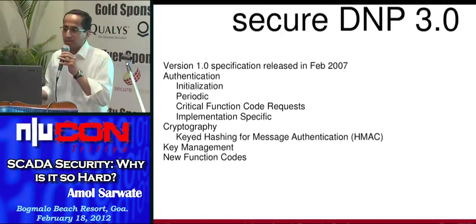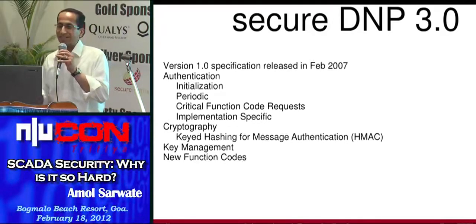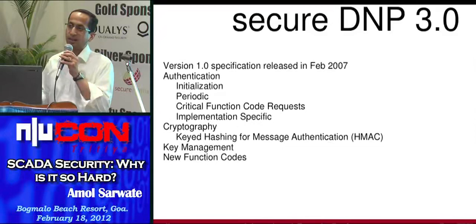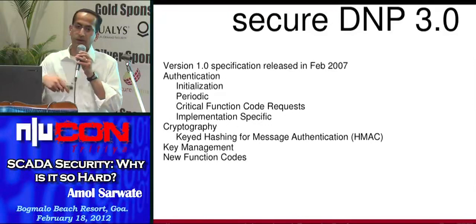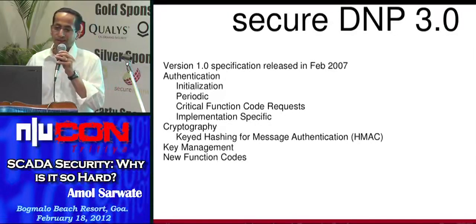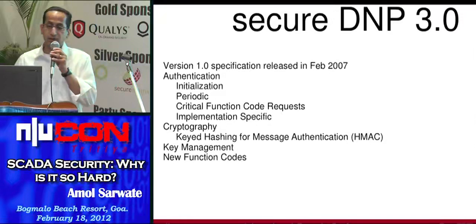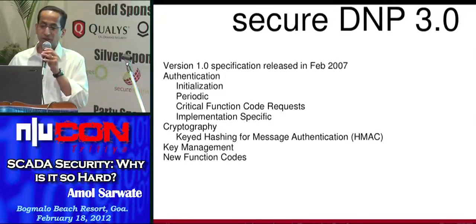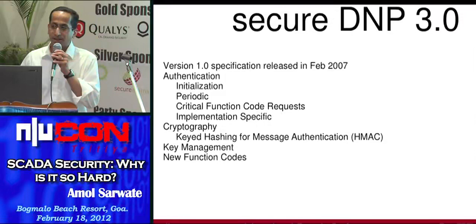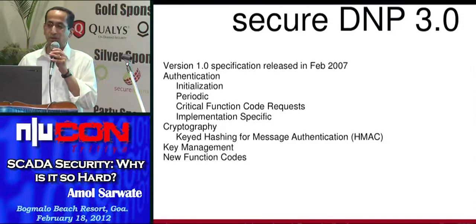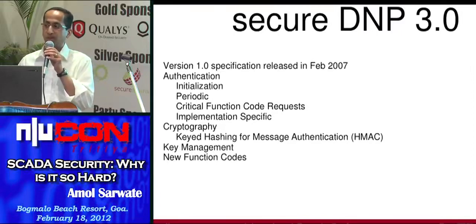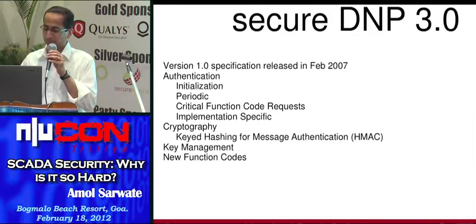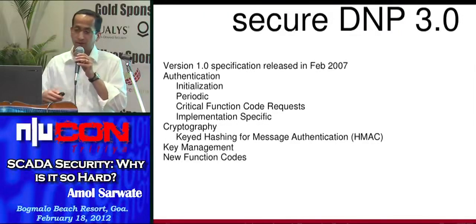So, well, all is not lost. What happened was in 2007, the DNP3 Foundation came up with an updated standard for DNP3, which provides a lot of the things that we were looking for here. It provides cryptographic key hashes for message authentication, which is HMAC. It provides key management functionality. So a lot of things that we said were just on the previous slide were not supported in Modbus and DNP3 are now supported in the secure version, a newer version of this protocol. So at least that is very good progress.